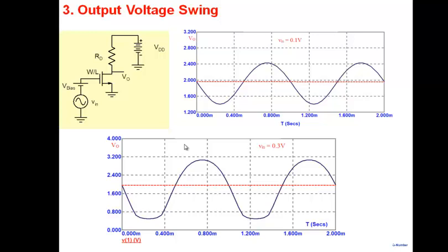Remember, the view of distortion that we have is harmonic distortion. So distortion is present even here. At this point, we have to calculate how much distortion is there. Second harmonic distortion will be present here. The only thing is, as you keep on increasing the output amplitude, eventually it starts going into triode region, and then the distortion becomes visible. You can begin to see clipping and all.